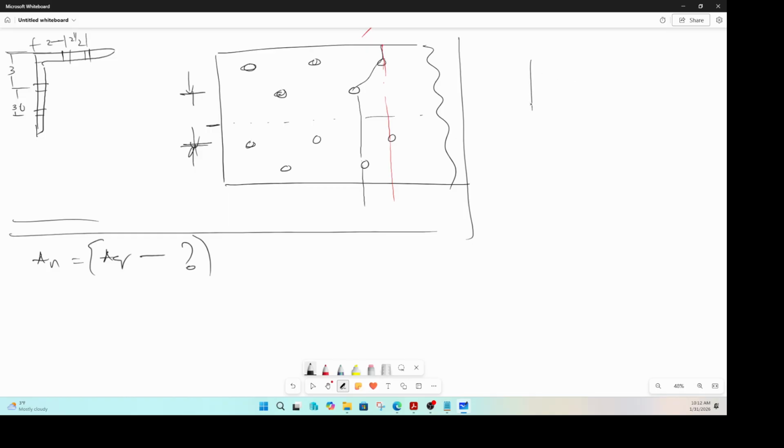If the holes were like that, then it's pretty easy to calculate the net area. But when you have a staggered hole, the length of the failure plane gets increased, and the code has some guidelines about how the net area can be calculated in case of staggered holes.